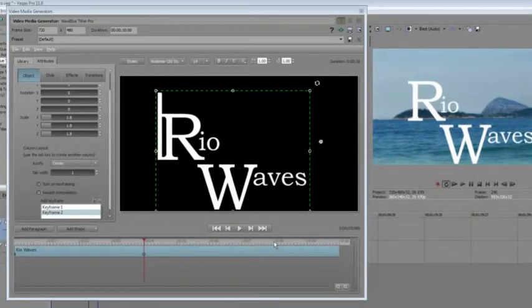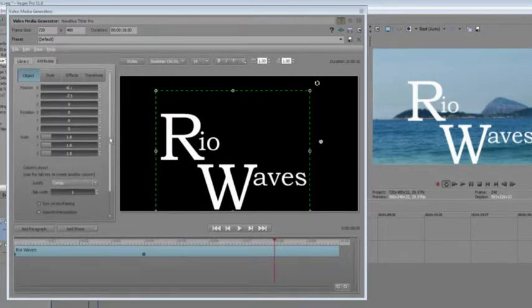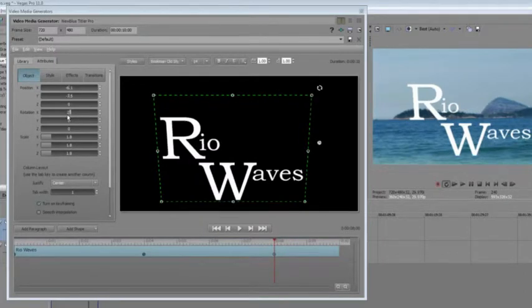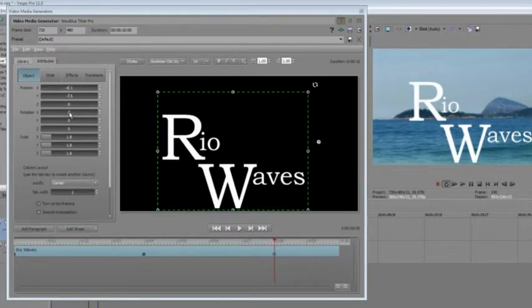And then maybe I want a third keyframe. At this keyframe, let's say we want to add a little bit of rotation to this thing. So I'm going to take the X rotation, and as I said, I prefer to work with the numbers over here. It just seems to give me a little bit more control. And as long as I'm here, let's talk about how you can control the settings using these tools. There are several different ways you can change the settings of these fields. One way I've already shown you a couple of times is to double-click the current value and type in a new value. I use that way quite frequently.